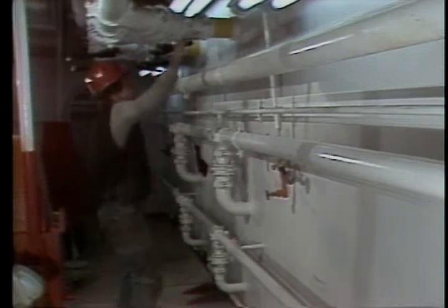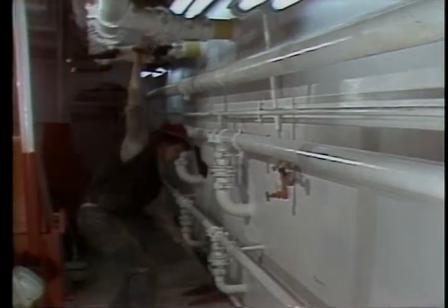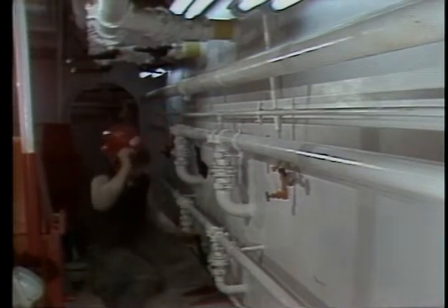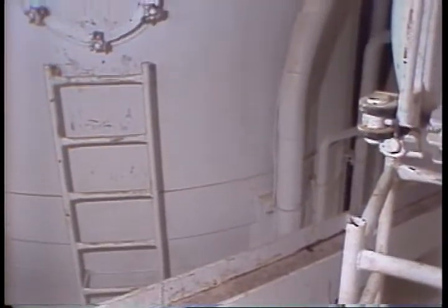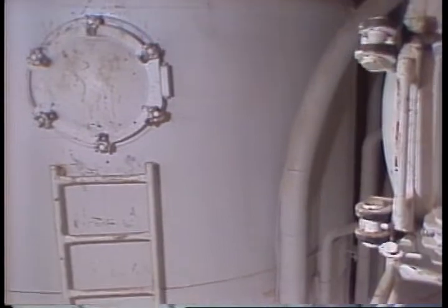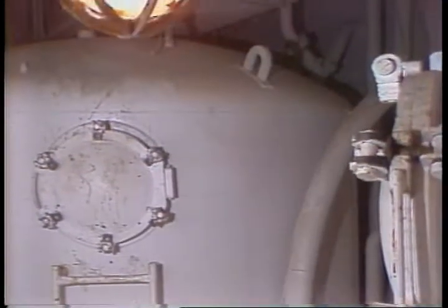First, we open the air supply into the source tank. You should be able to hear the air flowing. There's generally a pressure gauge that will tell you when it's at full pressure. If the bulk tank is pretty full, it won't take too long to pressurize. If it's low, though, it could take up to a half hour or more.